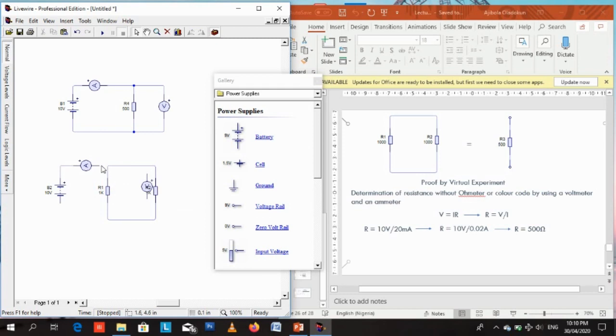So you connect, as usual, the ammeter to measure the current through the resistors that are connected in parallel, and then we connect the voltmeter across. The voltmeter is automatically across both of them, as the way we connected this shows. We will come to that later, but this is how to connect a voltmeter across resistors in parallel.